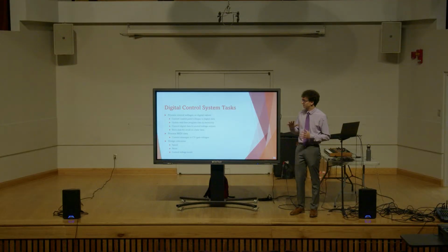And so the tasks for the digital control system that I have laid out thus far are processing control voltages as digital values. So that means you're taking control voltages from a panel and you're storing them as digital data in a processor, which is then going to be spat out to the analog circuitry.